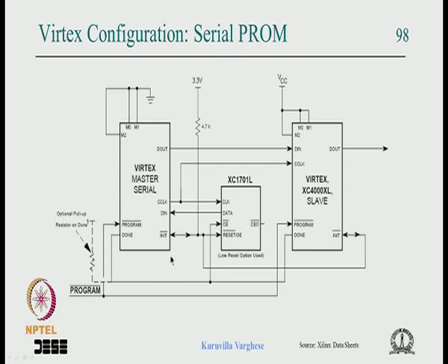One issue is that at the beginning these FPGAs have to clear their configuration memory, because it may not be a power on programming, it could be a reprogramming of the FPGA while the power is on. So all the configuration memory has to be cleared, and depending on the FPGA type and size, it will take variable time.